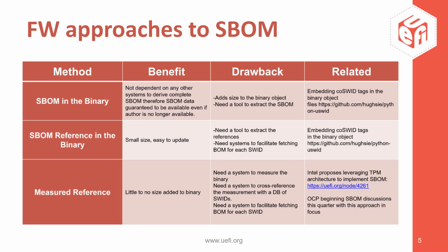Okay, so let's take a look at firmware approaches to SBOM. This table represents different approaches in implementing SBOM. I'll go through these and give a summary. First, you can have an SBOM in the binary. This is great because the BOM is intrinsically bonded with the binary. It's bad because it could require too much size in the firmware binary because you're adding all of that information. You'll also usually need some kind of tooling to extract the BOM.